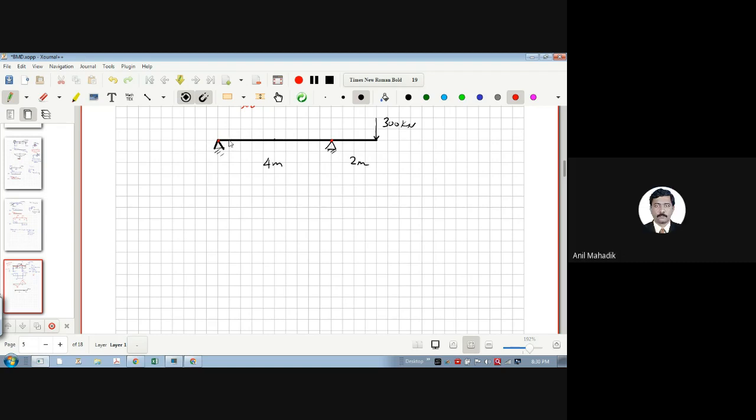This will try to go upward, there will be hogging, upward deflection. Something like this will be there, right? Yes, sir. Were you convinced? You might have seen this platform whenever we stand on a wooden plank or something, and if it is anchored, it will behave like this. So develop this deflection understanding for different problems, and whenever the problems are complex, just go to the software, put in the numbers, and see the deflected shape.